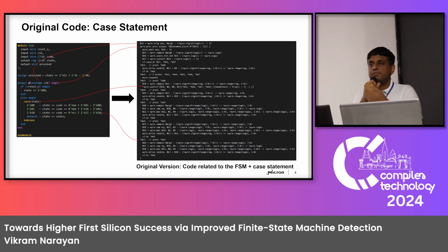Yes, it maps into a switch, and once you have a switch, you can identify the states. And once you have this representation, we can construct a truth table and then identify it as an FSM. Now, in case this is not identified as an FSM, the compilers will default this into lines or statements. And then the coverage is identified as whether it was hit or not hit. But the truth table logic is totally gone.